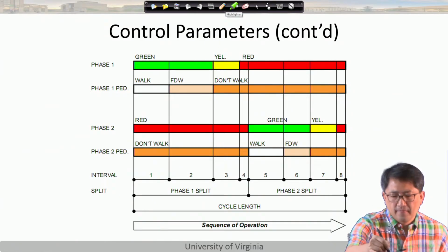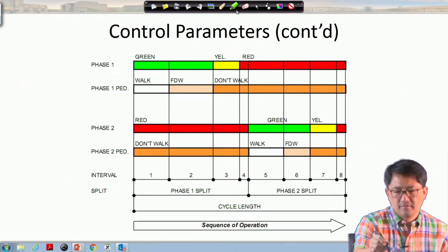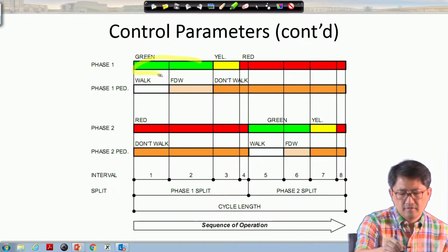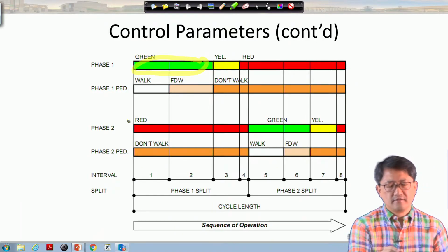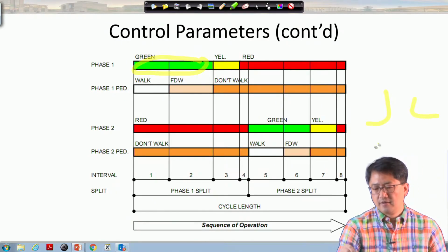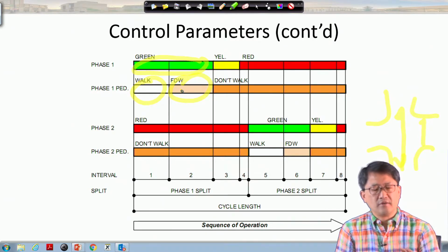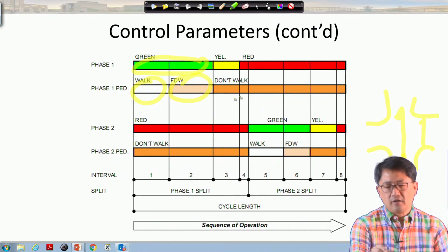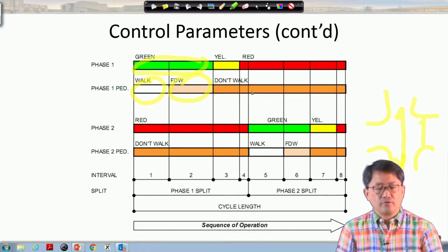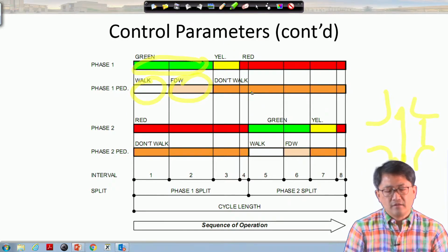Okay, thank you. So during the green time, we have a portion of the green, obviously this is for when you have intersections and this guy is showing the green here, then they will have a crossing, right? So the green duration is divided into walk and flash don't walk. It's a fairly long flash don't walk, and now a lot of intersections are showing the countdown. They show the remaining pedestrian walk time, so that's good. And then a fairly long don't walk as well. So this will allow pedestrians and bicyclists to cross.